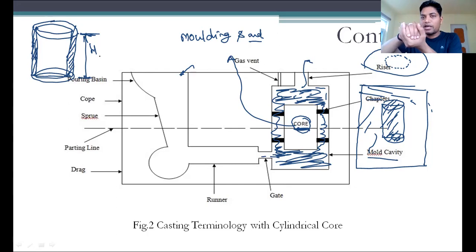But when it becomes completely solid, can I remove this cavity? I cannot remove this cavity. If we are using wood or any hard material, it will become a part of this. We do not want it to become a part of that. So that's why we are using this molding sand.